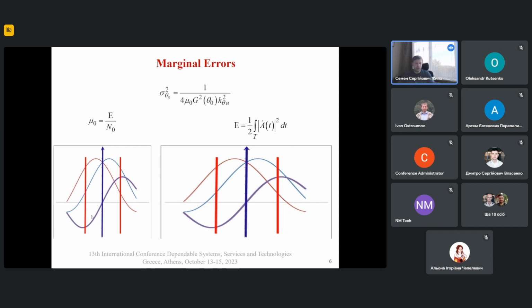But in this case, we have another restriction. It is called the unambiguous measurement of the angle. And in this case, we make narrower these limits of unambiguous measurement of the direction. And to increase this region, it's necessary to use a wider antenna. But in this case, we have another contradiction. The limit errors of angle measurements make this situation worse.